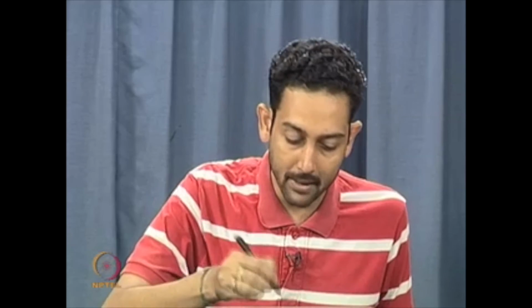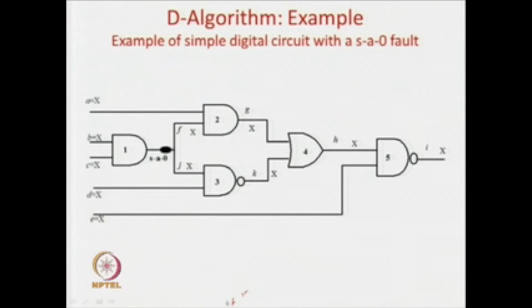So that is the brief discussion of why we are most prone to go for random test pattern generation as much as possible and apply the D algorithm only for difficult-to-test faults, because many times you have to go for a lot of backtracking. Now we will see an exhaustive example, which will tell you how exactly the D algorithm works, and you will also see many cases of backtracks, so that it gives a good highlight of the D algorithm.